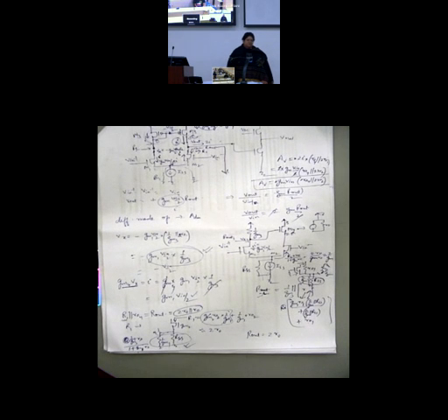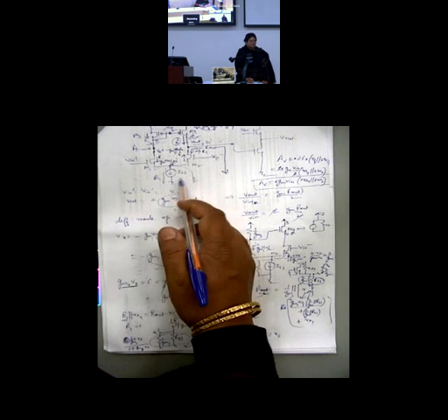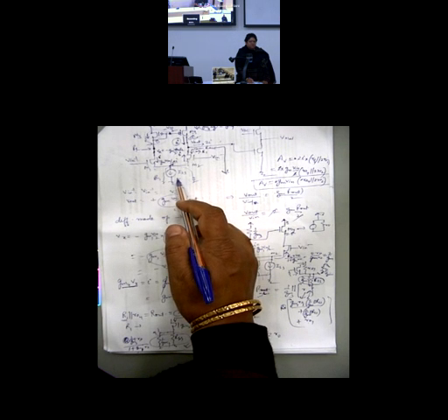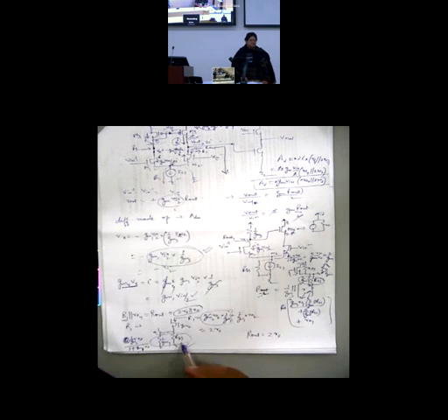And here I cannot take this node to be AC ground because it is not. Even if you are applying your input differential, it will not come to AC ground because of the unsymmetrical load structure. But still, you would be able to get a difference mode operation. Just make your RSS large so that you can make this approximation and then everything will go well. So I cannot use a diode connected MOSFET as my ISS. Can I use? No. Because the moment you use a diode connected MOSFET to supply ISS, RSS will become 1 by G.